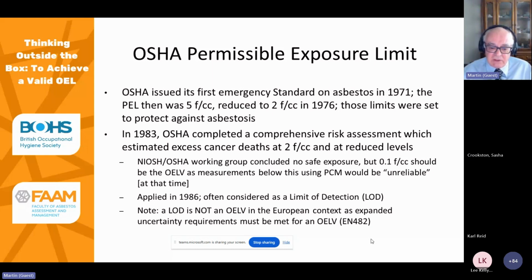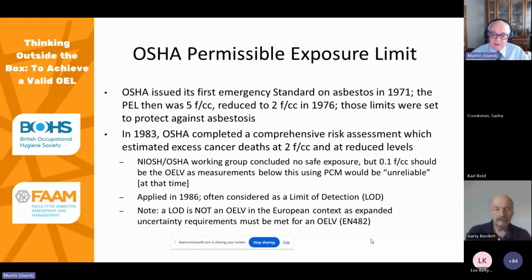Now, a limit of detection is not a limit value in the European context, as EN 482, the European standard, sets expanded uncertainty requirements around the limit value, and limits of detection usually don't have those requirements.